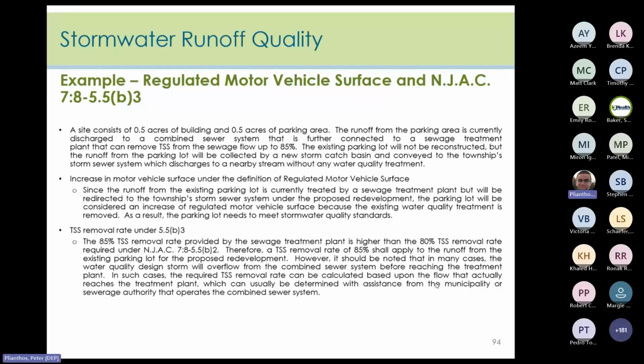So since the runoff from the existing parking lot is currently treated by a sewage treatment plant, but will be redirected to the township's storm sewer system under the proposed redevelopment, the parking lot will be considered an increase of regulated motor vehicle surface because the existing water quality treatment is removed. As a result, the parking lot needs to meet the stormwater quality standards.